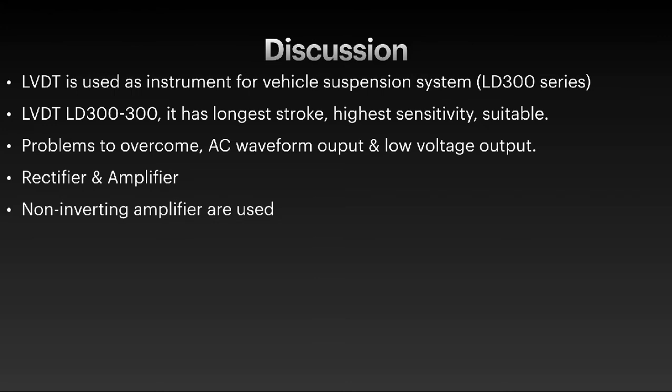However, there are some problems that might occur, such as the output of LVDT is an alternating current, which has no polarity, and also the voltage output is too small. So to overcome this, rectifiers are used to overcome the problem of AC output waveform, and the amplifier is used to amplify the voltage output.